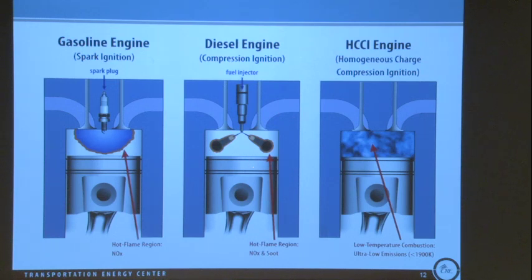And so as the temperatures come up from ambient to about 750, 800 Kelvin, you start to develop low temperature reactions or low temperature ignition. And those generate intermediates that then get bootstrapped into hot ignition, which occurs typically at about 1100 to 1200 Kelvin or above, and eventually you form a diffusion flame around the whole thing that is lifted a little bit, stabilized off of the injector.